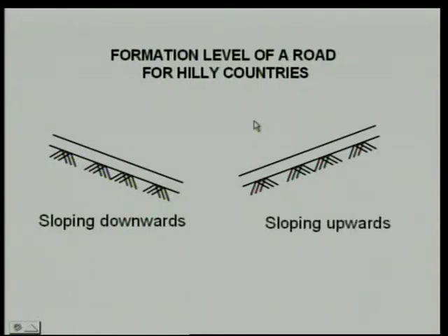Now, let us see the formation level of a road for a hilly country. For hilly countries, the topography of the ground may be either sloping downwards or sloping upwards. Generally, in hilly countries, the nature of the ground may be either in banking or in cutting. So, the earthwork excavated from cutting is used for banking purposes within the economical limits for the construction of the project.